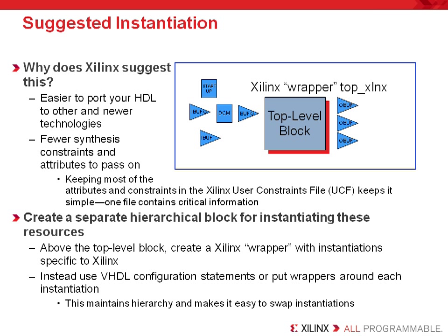As I mentioned earlier, we suggest that you keep your instantiated components in one location. Now, most designers place the Xilinx specific instantiations at the top, or one level down, but never more than that. This makes it easy for the user to locate and maintain the design and port your code to another device family or technology later if necessary. We also recommend keeping your pin assignments and pin attributes in your design's UCF files so all the Xilinx specific constraints are removed from the HDL. This makes your code more generic.